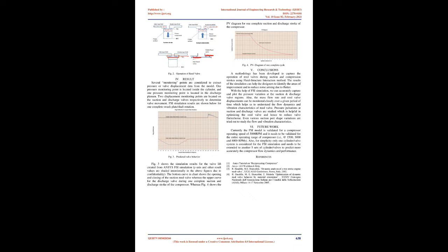Throughout the valve opening, new fluid elements will appear between the valve and the seat. Since there is no remeshing but the fluid mesh is just deforming, extra elements are needed under the valve, which first perform as rigid seat and later as fluid. The immersed boundary technique allows this change in the nature of an element thanks to a modification in its viscosity.